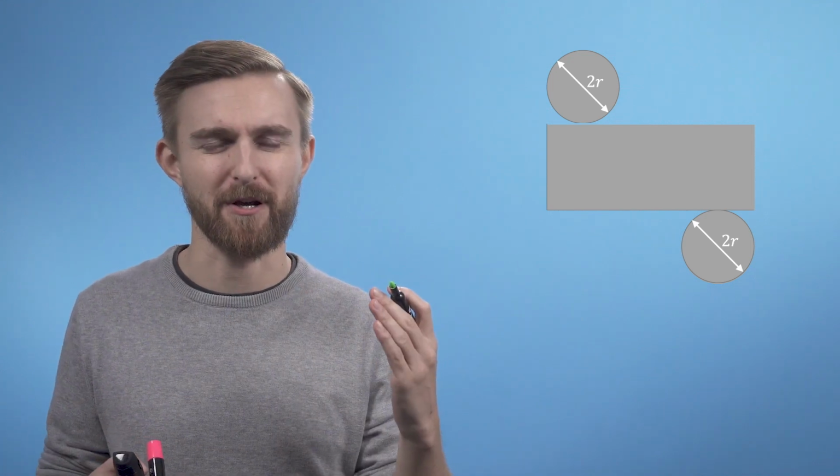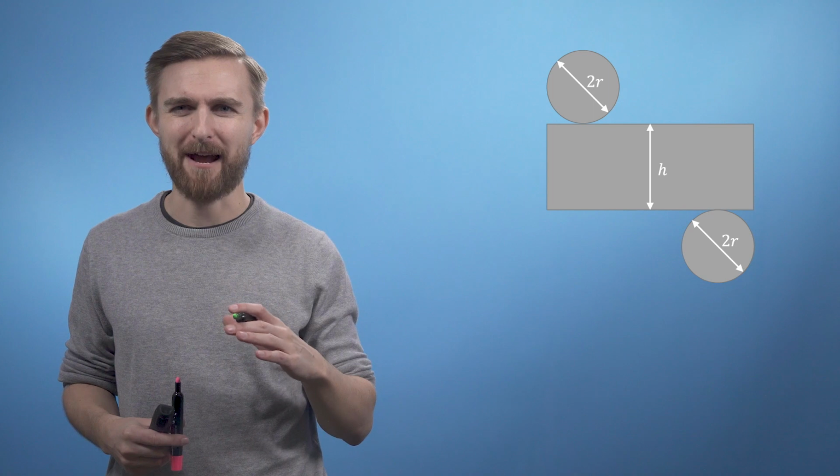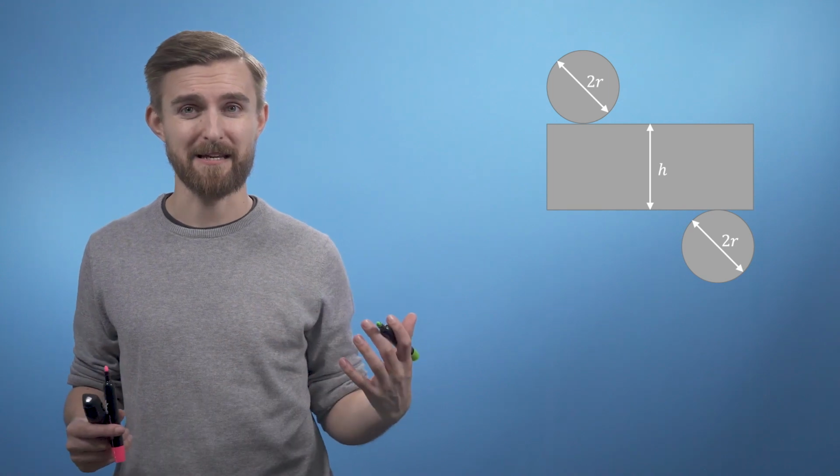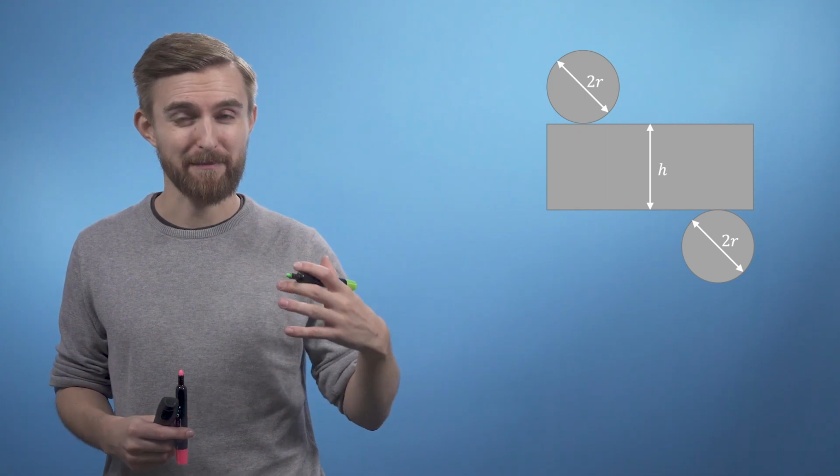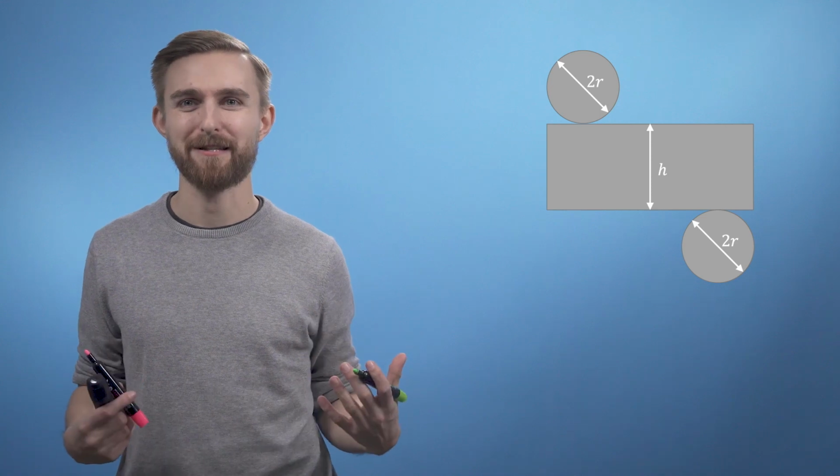Imagine that you wanted to manufacture a metal can. So you need to understand the relationship between the various key design parameters. We can start by writing a reasonable approximation for the can's empty mass m by breaking the area down into pieces. So the circles on top and bottom are pi r squared each, and when we unroll the body we get a rectangle where the width must be the same as the circumference of the circle, i.e. 2 pi r, and we'll just call the height h. So, taking these areas and multiplying them by a thickness t, we get the total volume of metal in the can. Finally, multiplying this by the metal's density, ρ, we get its mass.